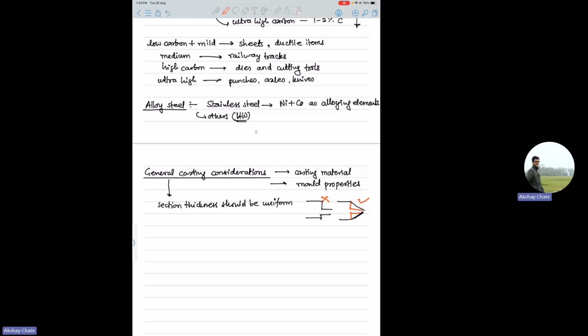Okay, and it should be avoided to have a concentration of metal at one place. So you need to provide some web centerings in a staggered manner, so that the hotspot doesn't fall there. Thin ribs should not be directly joined to the thick ribs, as I showed here, and tolerances, etc., you have to give. These things are pretty common, but many times people don't follow this. That is the problem.